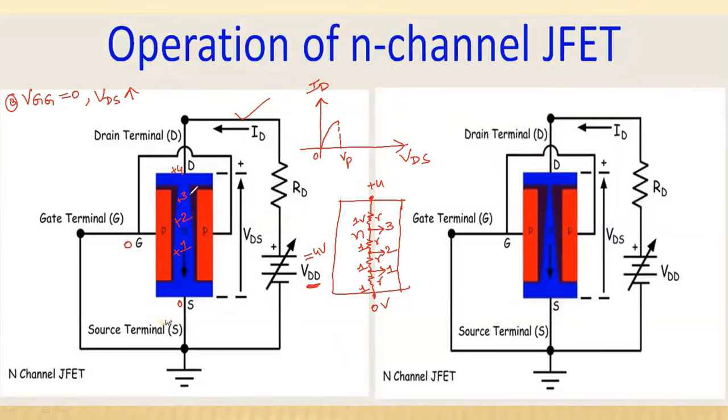And this voltage is more. So therefore, as the reverse bias voltage is more, the width of the depletion region is also more. So here the width of the depletion region is more, here at plus 3 volts. Similarly, now you have plus 2 volts. This is a lesser reverse bias voltage, so the depletion layer width is also lesser compared to this place.